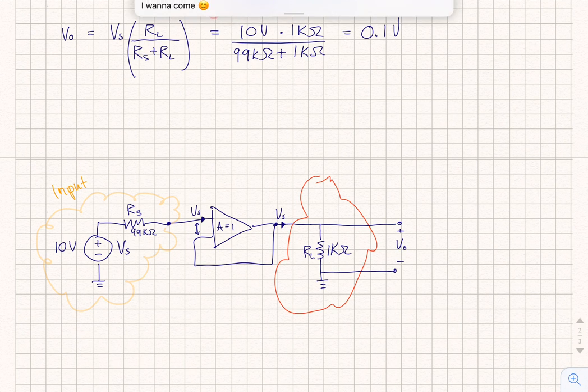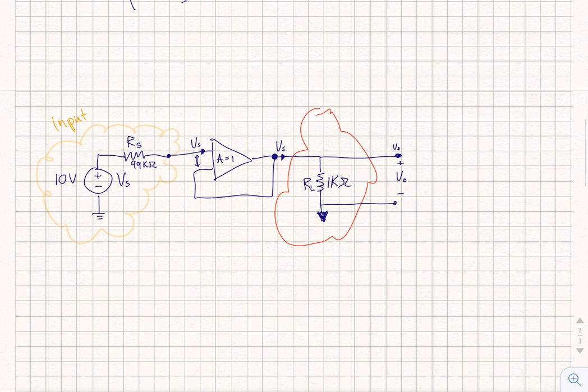And so because there's VS over here in this output junction of the unity gain buffer, you're going to have VS over there, and this VS right here is relative to our ground right here, and so that means that our V out is going to be VS again. So it's a really useful trick, just adding in this unity gain buffer, and then it matches our impedance.